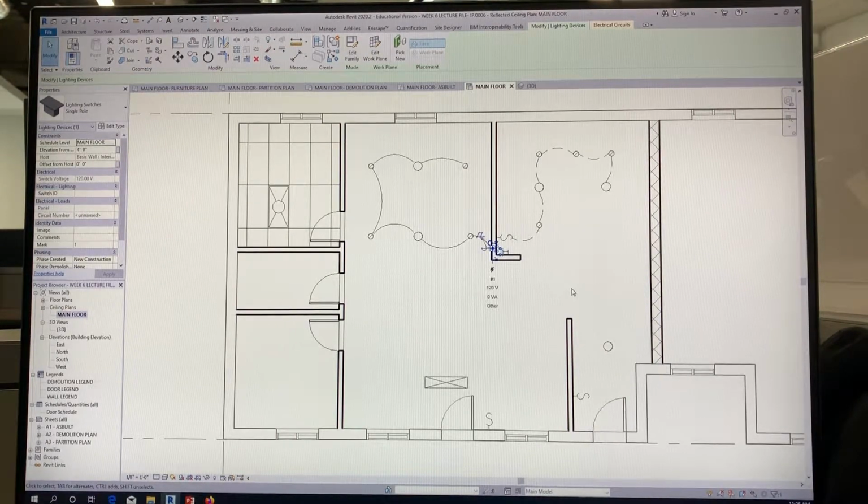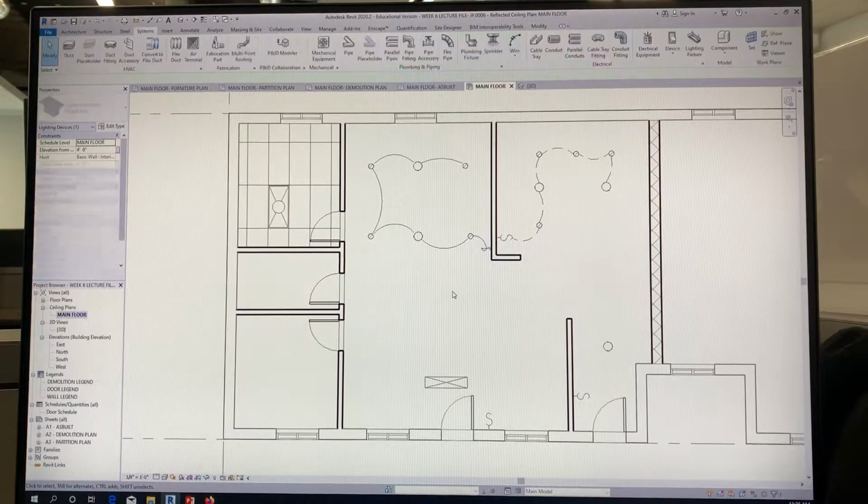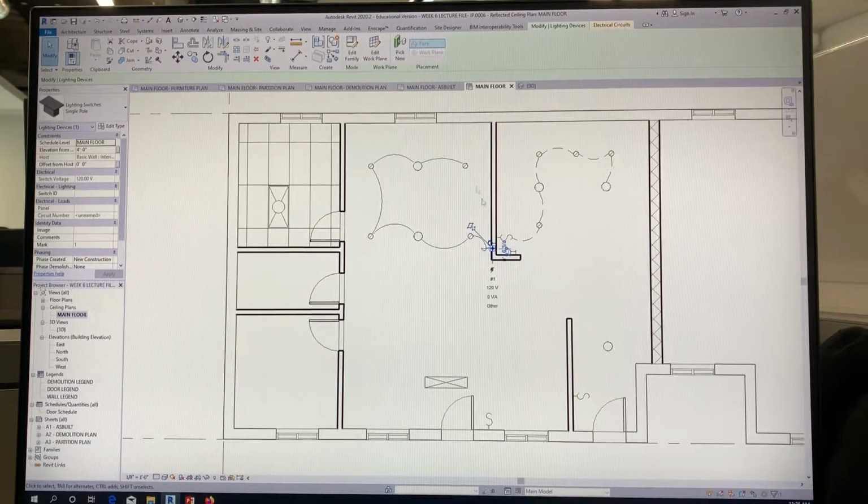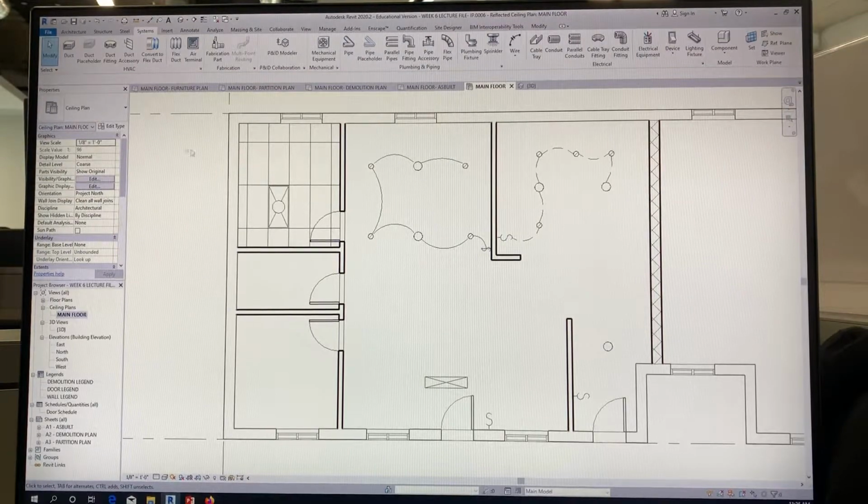So, Sandra, sorry, it shows me power, but when I select them all, the power goes away. Okay, so that means you've accidentally selected power already. So go ahead, take it, delete it, and reinsert another one in there. Make sure not to select this and then select power. So again, put a new one in, delete that, put a new one in. Select it, hold down your control key, select all the other lighting, and then click power.